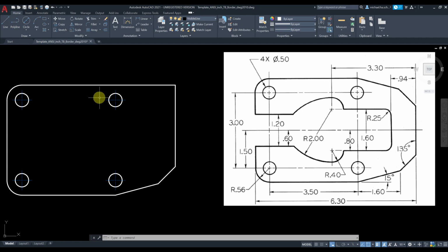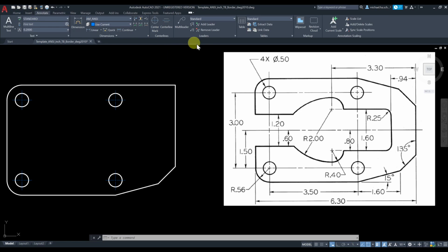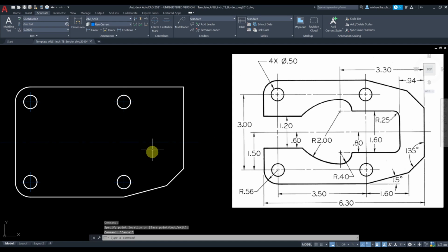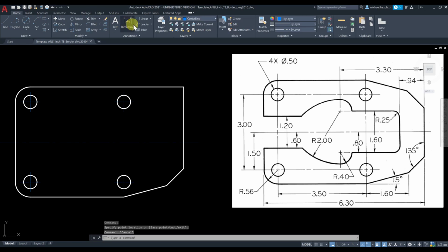Before doing that, let's go ahead and add some sort of center line between this and this. You can grab that and move or extend the center line furthermore, and we're going to go to the Home tab and click on mirror and select these two.